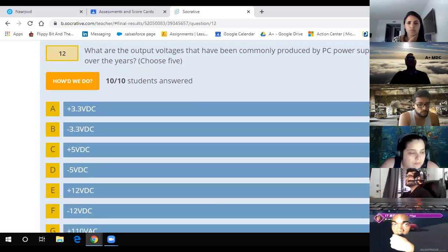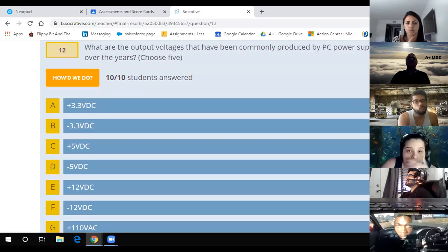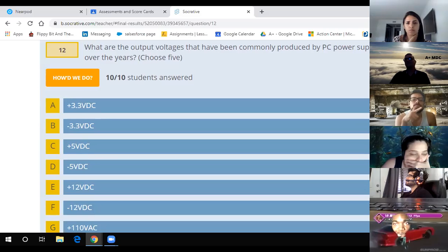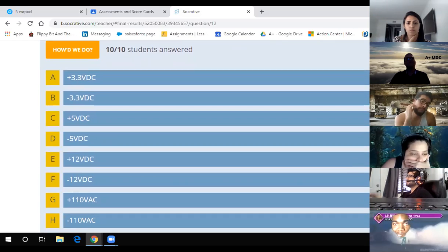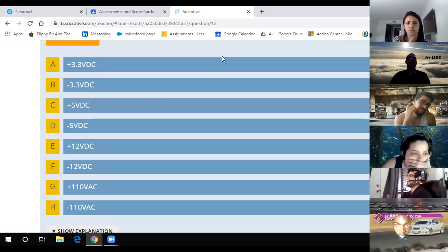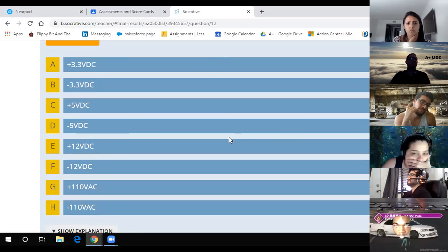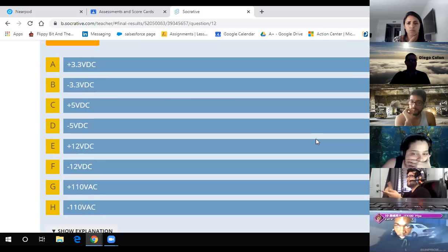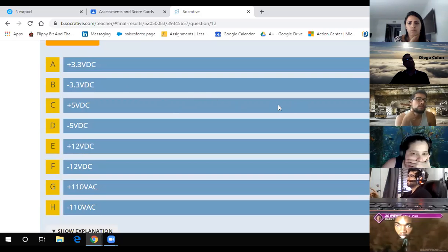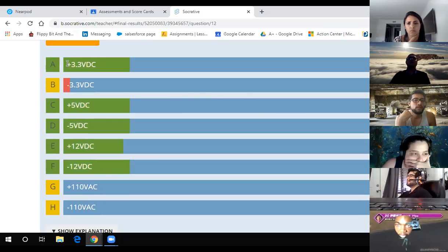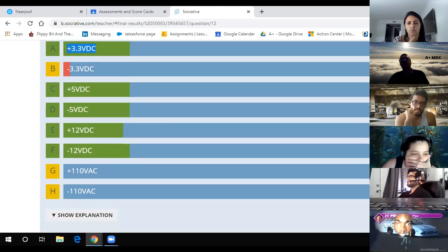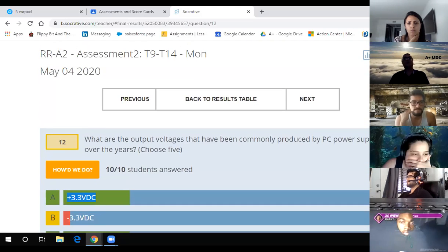Lázaro, your turn. Okay. What are the output voltages that are commonly produced by PC power supplies over the years? Choose 5. That's 12, 5, 3.3. I know it's talking about plus and negative, so it's going to be plus and minus 12, plus and minus 5. There is none for 3.3 volts, usually, commonly, just a plus. Okay. 3.3 positive, as he stated, and all the other ones positive and negative. There is no negative 3.3 inside these power supplies.